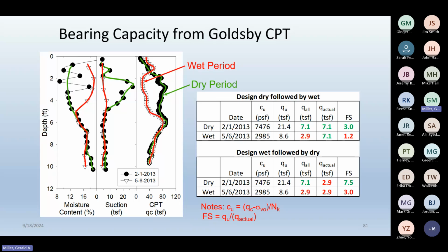assuming that we've given that high of an allowable pressure, but that's what the soil theoretically would bear based on those strength estimates. And again, taking Jim's point in hand, maybe that 20 should be a 30 instead of a 20.